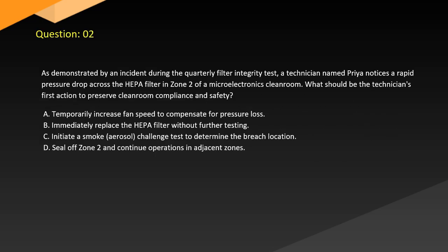Question 2. As demonstrated by an incident during the quarterly filter integrity test, a technician named Priya notices a rapid pressure drop across the HEPA filter in Zone 2 of a microelectronics cleanroom. What should be the technician's first action to preserve cleanroom compliance and safety? A. Temporarily increase fan speed to compensate for pressure loss. B. Immediately replace the HEPA filter without further testing.